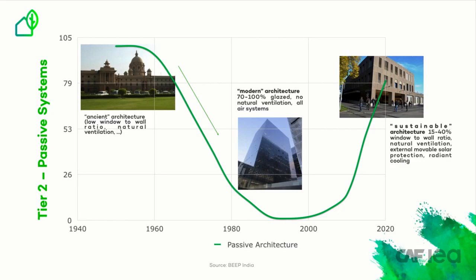In hot and dry climates, massive walls and roofs are often used for their thermal storage and time lag effect. Windows are small as the sun is very intense. In hot and humid climates, building designs favor ventilation and shading.